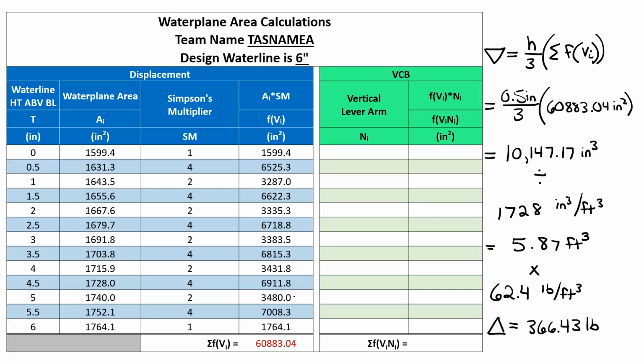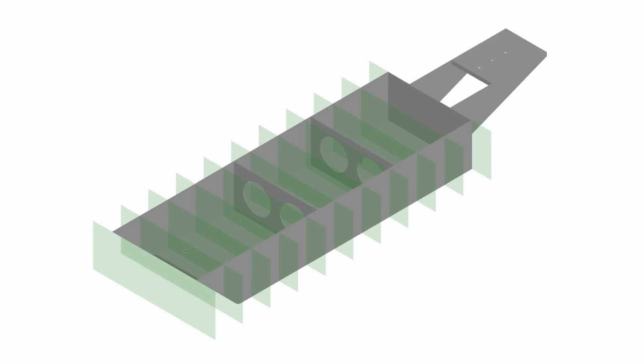I have the example boat here, and now it's separated by vertical planes called stations. Each of these stations intersecting the boat's hull is a station area. So my station areas would be these areas. And of course, because my draft is only at a certain distance, I'm only calculating the station area between here. And for my station areas, I'm going to assume my draft is 6 1/16 of an inch.